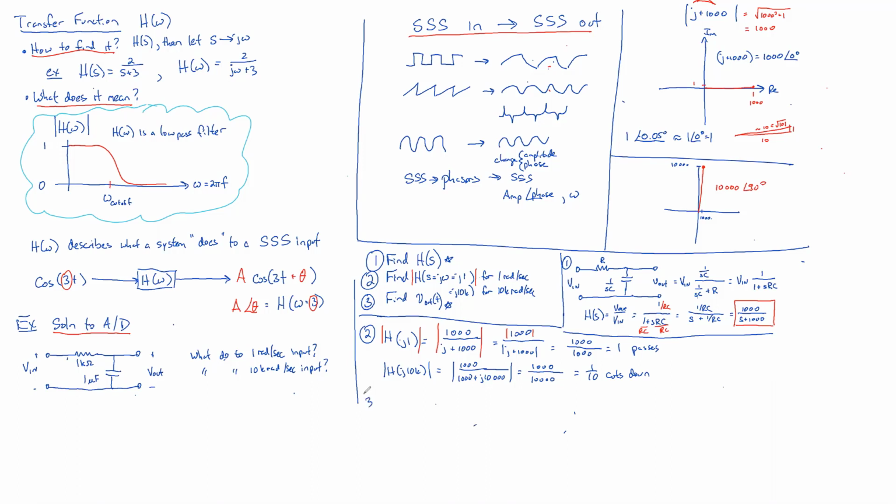And we can do that just when we find V out. So V out of t is going to be equal to cosine of 1t or 1/10 cosine of 10,000t. And this is the low frequency, and this is the high frequency. Passes and stops. Questions about that? That's the first filter that you've analyzed.